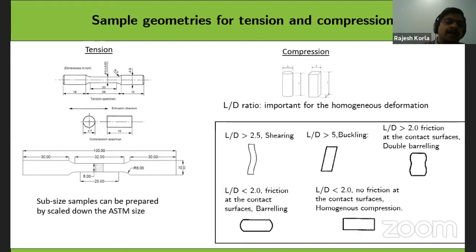For example, if your sample is forged material with more thickness, people go for a cylindrical cross-section sample. If your sample is in sheet form and you want to study the microstructure of the deformed material in the gauge portion, then it is better to go for the rectangular cross-section dog-bone shaped tensile sample, because you can see the microstructure of the sample after the deformation also.